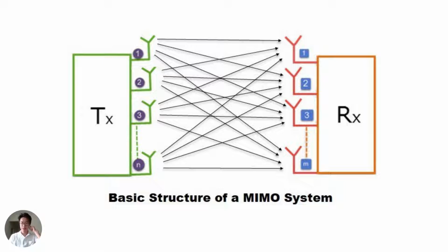different areas. This is different from an array antenna, where multiple elements are combined together with a single input. They just have beams protruding in different locations and different angles. But with a MIMO radar antenna, you have different outputs with different inputs.